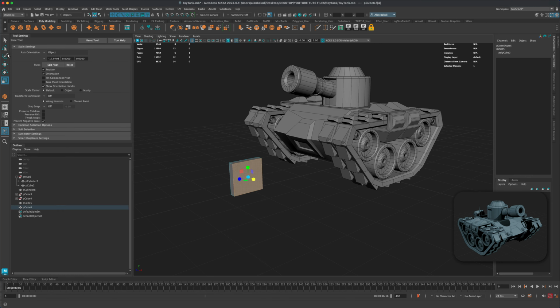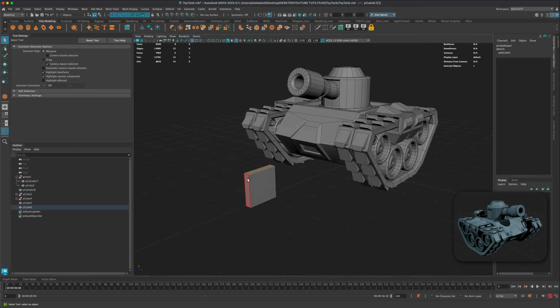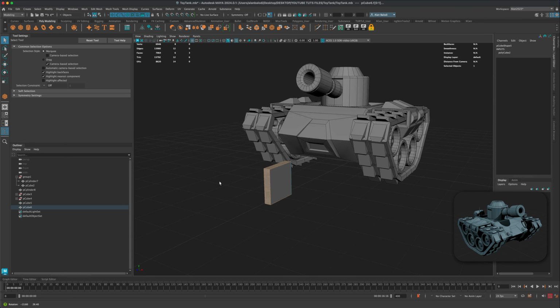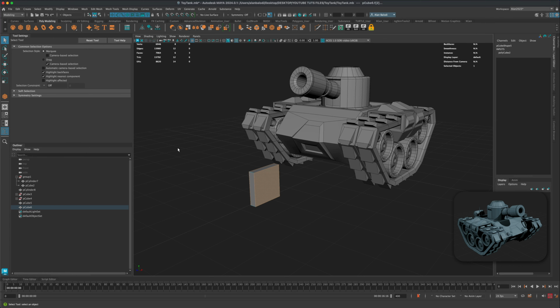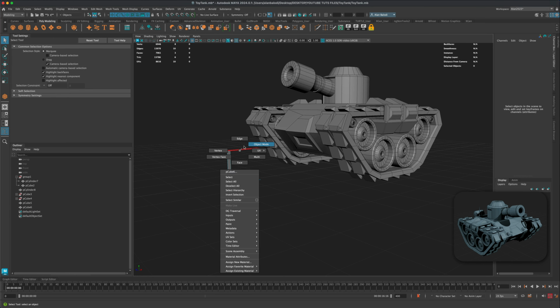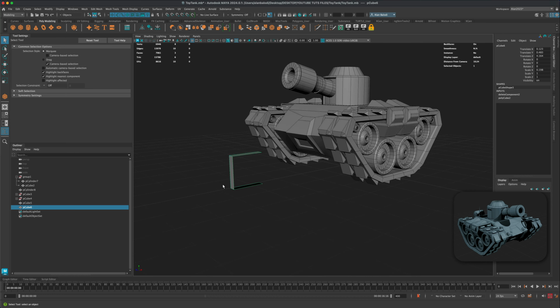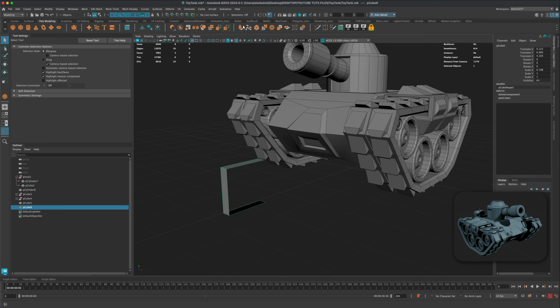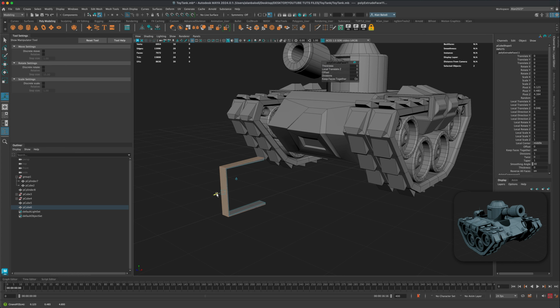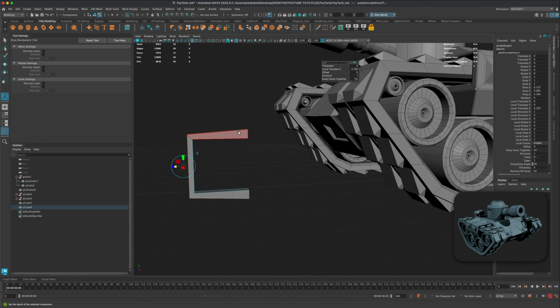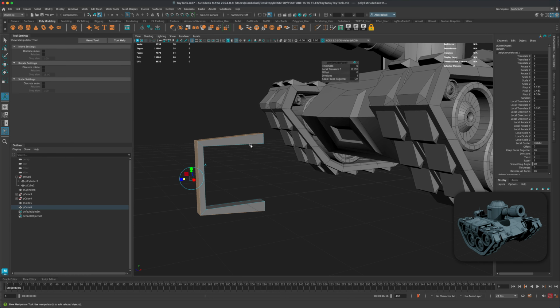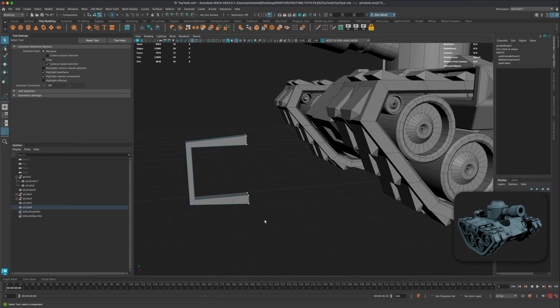And essentially all I need for a handle is just these pieces here, right? That's all I need. So let's do a select inverse, and let's press delete on everything else. And now if I go into object mode and grab the entire mesh and do an extrude, I can simply add thickness to it, and you can see it's extruding not perfectly, right? And I'm kind of liking that. It's doing this interesting angle, so I'm going to leave that and use it to my benefit.